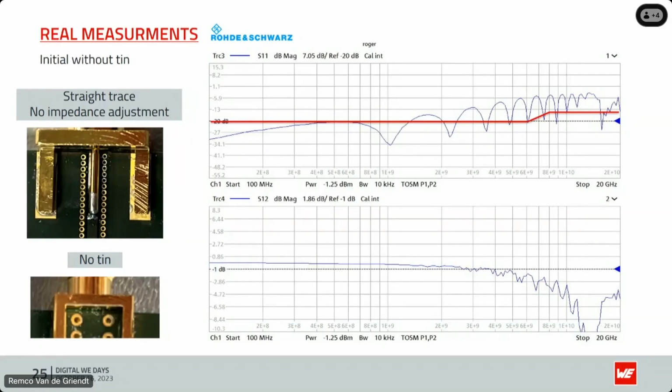If you're looking at the return loss, -1 dB means that around 19% of your signal power is lost. That's also not for really high frequencies. In this case, I think for 434 megahertz, for instance, it will be okay. But if you go higher, then you really have a problem. So not for Wi-Fi, Bluetooth, and that sort of thing.